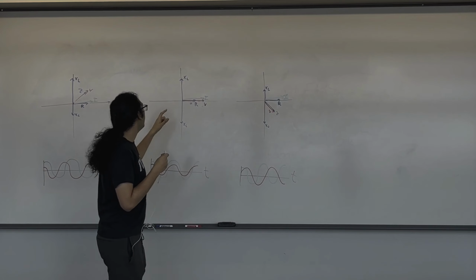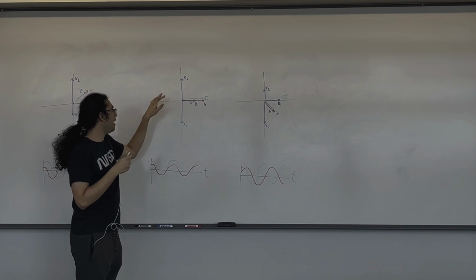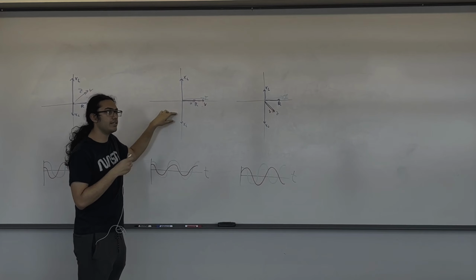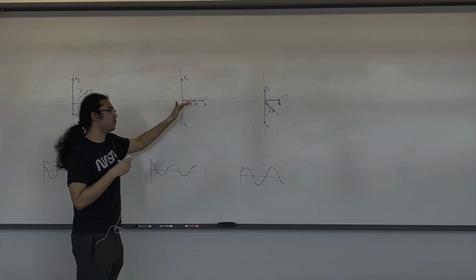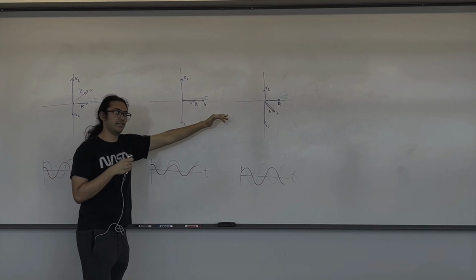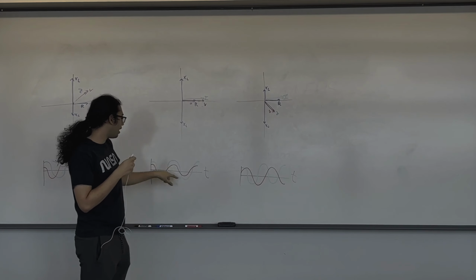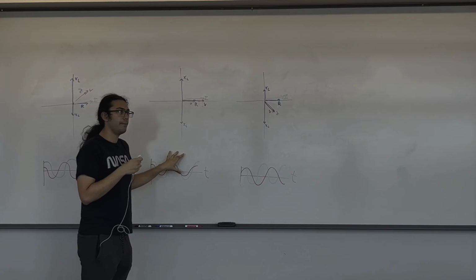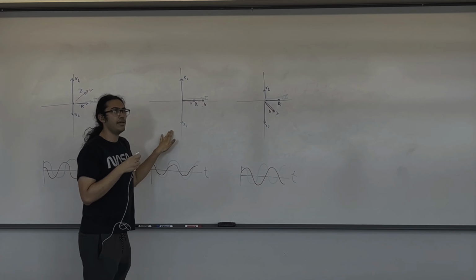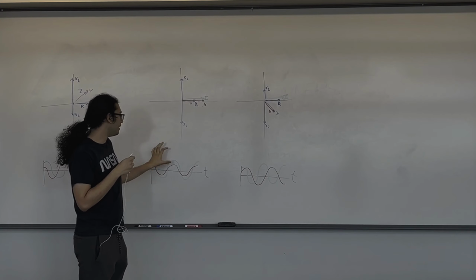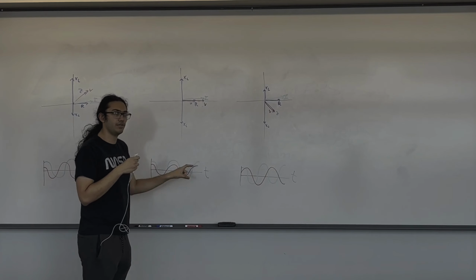And in the middle here, we have that the inductive and capacitive reactance are equal to each other. So our impedance and voltage are all lined up on the horizontal axis. So as we start rotating this, our peaks and our troughs are going to line up perfectly. And this is a special type of situation which we call resonance. And resonance is important because it gives us this lined up current and voltage.